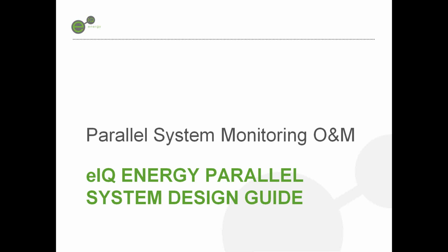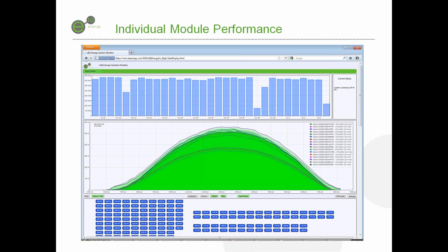So let's talk a little bit about that monitoring and O&M stuff. We've got each one of our vBoost units, as we talked about earlier, providing its actual telemetry information. So for every 5-minute increment within the day, you can see what each individual module is doing. And of course, this is very important because you're going to be able to spot immediately where there's problems. And the graph that we have up here on the screen is kind of showing what it looks like. I'm plotting different vBoosts against each other, so now I can see how they're performing relative to one another. And in this particular installation, I actually have 2 technologies. And you can clearly see the bands of one technology versus the other, and kind of what their performance is throughout the day.